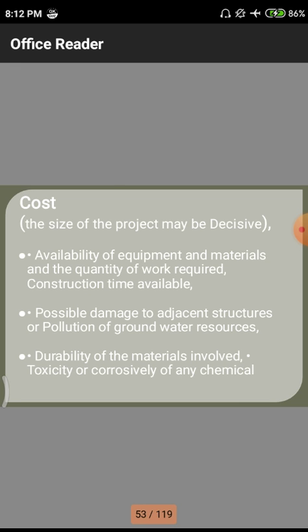If the time period is very short, that means we need to use a huge amount of equipment and workmanship. If the time period is very long, that means we have to use a smaller quantity of material to save money and other costs. So first of all, we need to focus on the availability of equipment, whatever we have, such as bulldozers, cranes, draining equipment or filling equipment. Whatever we require, we first need to notice, depending upon the project cost and site availability.